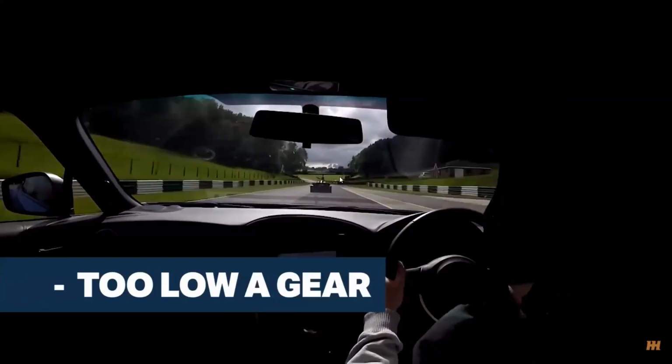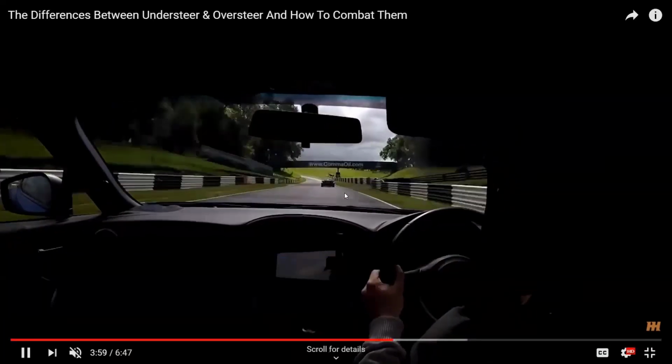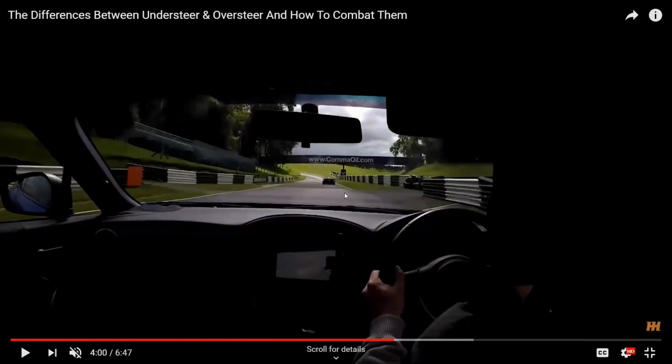Okay, oversteering also happens in the case of too low a gear. It is not only when the rear wheel is spinning that oversteering will happen. If the rear wheel is skidding, oversteering will also happen. The rear wheel will skid, for example, if the vehicle is moving at 80 km/h and we directly reduce the gear to second gear.